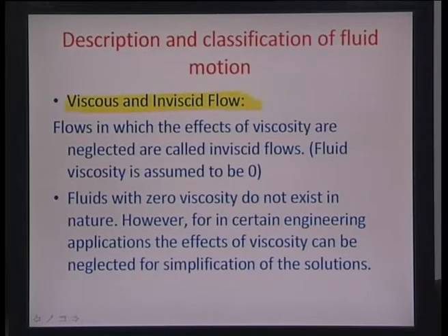Again I would like to reiterate that these concepts are very important particularly for micro scale flows, because essentially all micro scale flows have very prominent viscous forces and effects, okay, which makes these flows behave totally differently than their macro scale counterpart. So, intuitively whatever you think would normally happen to a set of fluids in macro scale can really not be translated to the micron scale transport.